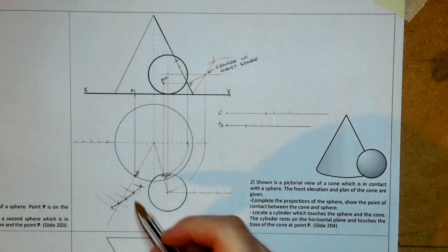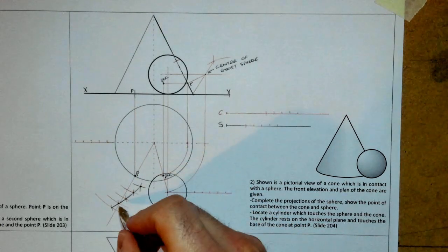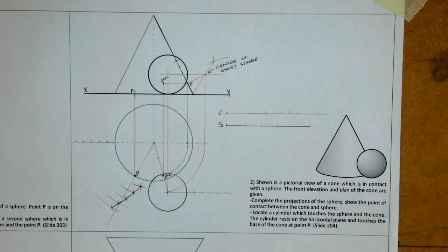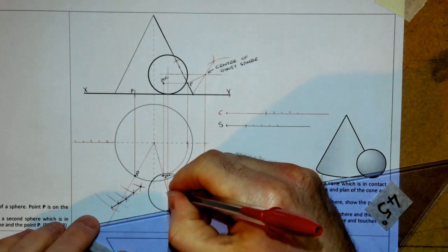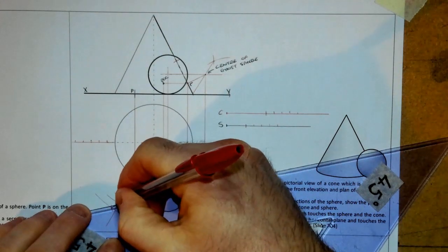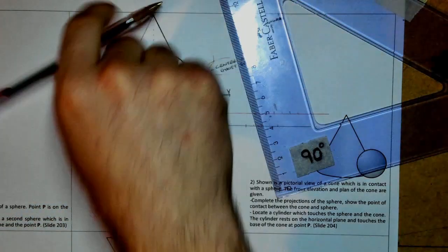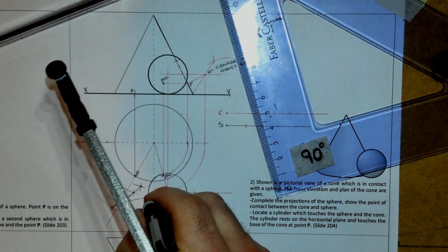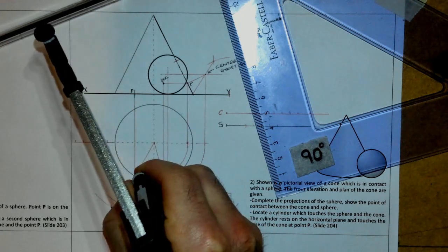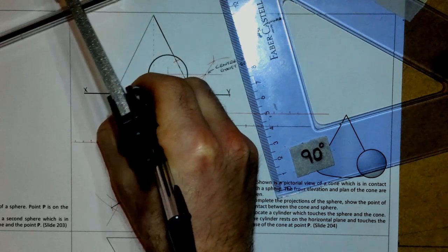Okay. But we know our centre is out along this line here, so where it crosses that line there, which is right here, we have now found the centre of our cylinder. So at that point there, what we can actually do is draw in our cylinder. We know a cylinder, when we look down top of it, is a circle. So if I'm accurate here now, our point of contact of a cylinder and a sphere should be where the two centres connect once again. So I'll join the centre to the centre, and depending on my accuracy, the method is right. Okay, our point of contact should be here. That's my other POC. Obviously a POC up here.